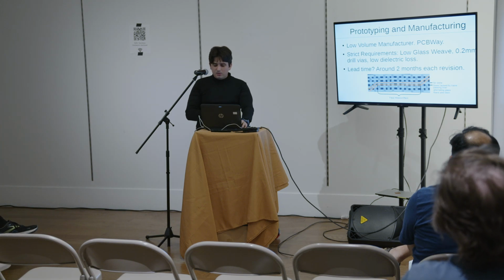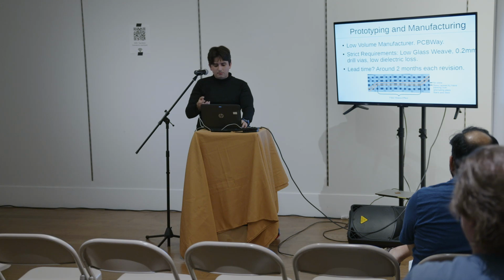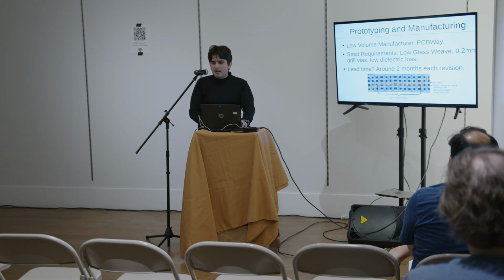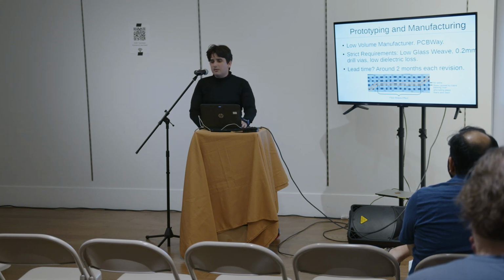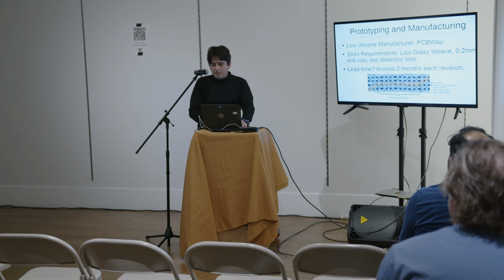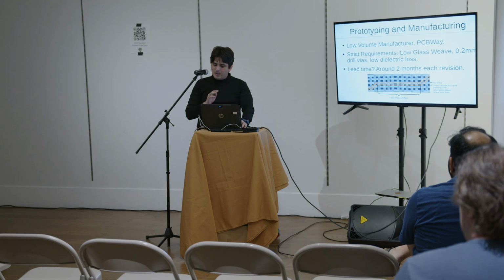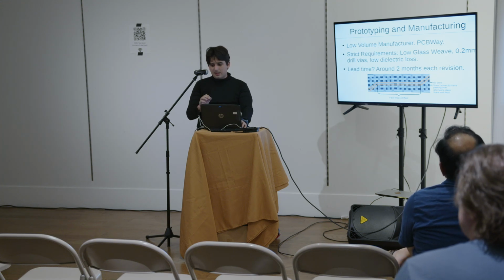You usually want to make sure that your manufacturer can comply with your required specifications, because if you finish the board layout and it turns out it's too expensive to manufacture, or maybe worse even, maybe it's not possible to manufacture at all, that would make you pretty much lose your time. You will have to make it all from the beginning. So for this kind of projects, you really want to make sure your chosen manufacturer can handle all the required specifications, and you want to make this clear from the beginning.